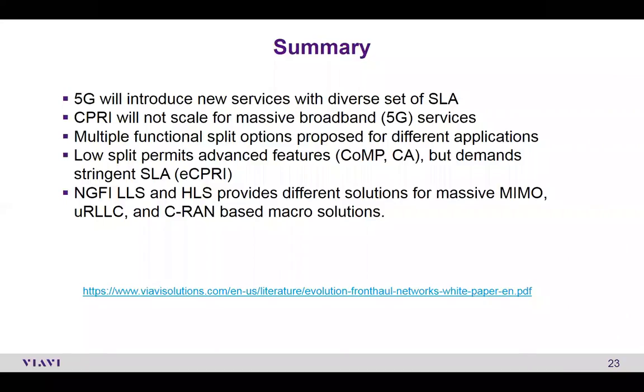Therefore, I expect still the 4G to be around for a long period of time. And for those applications, obviously, you would still have CPRI. CPRI is very cost effective. You would use that for LTE type of carriers, 20 megahertz, even 40 megahertz, lower number of MIMOs, 2x2, 4x4. All of those could still work with CPRI, maybe even with some compression, you can get even higher order MIMOs in there. And therefore, I think that CPRI will still be with us for a long period of time.